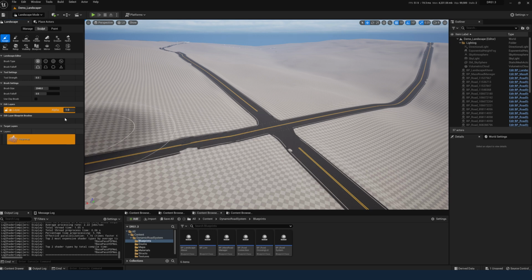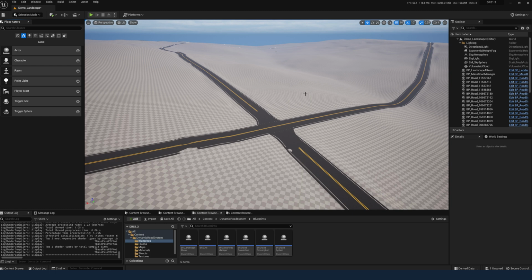This layer is my only layer, and it's the one that has my height map associated with it. It's also important to note that this blueprint is using a destructive method in order to get these results. A destructive method means that when you save this landscape with these changes, there's no way to get your landscape back to its original topography.